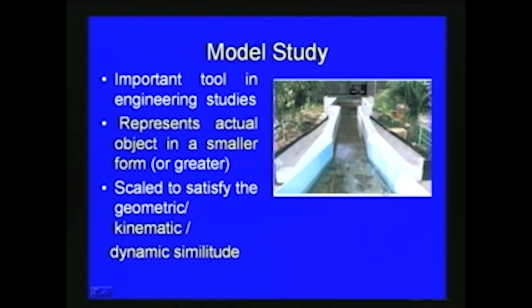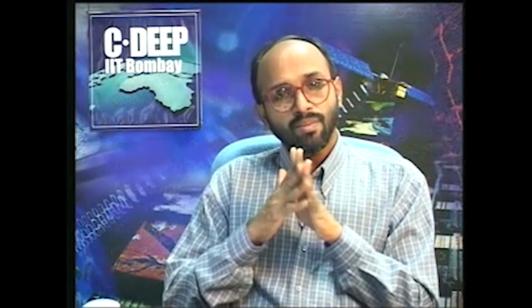Here we have done a model corresponding to an open channel, and here we provide a pump sump. This case was done for an industry, to see what happens in the pump sump when a large quantity of water is pumped out. How the flow behaves is very difficult to solve with a mathematical model or theoretically, so we construct a model for this kind of problem.